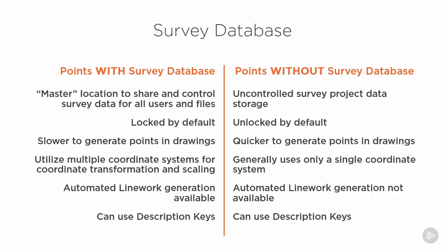The points with the survey database are locked by default. The points without are unlocked by default. You can still lock those points without the survey database by manually locking them with options. With the survey database, it's a little bit slower to generate the points in the drawing. It was a little bit quicker for us to do it without.